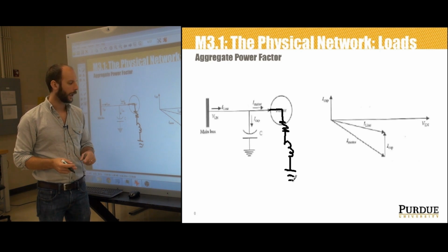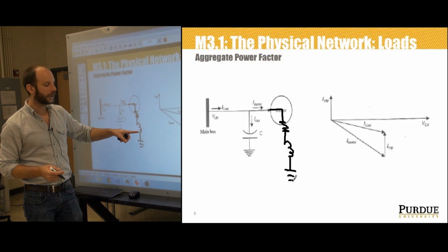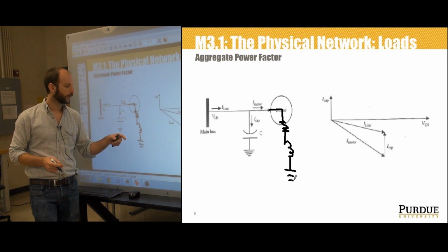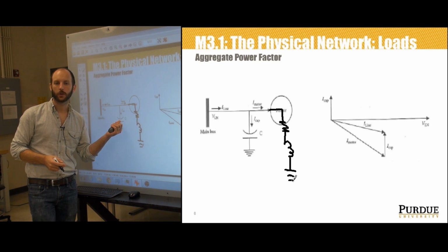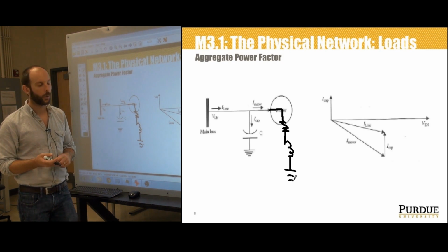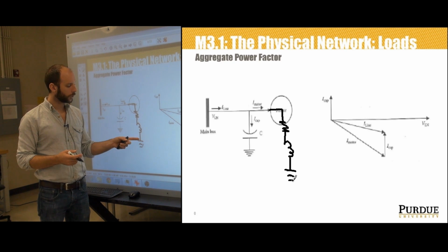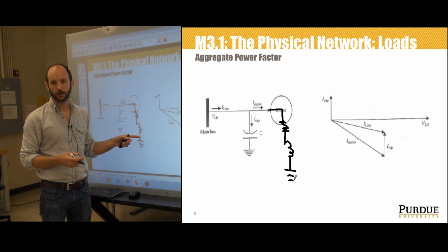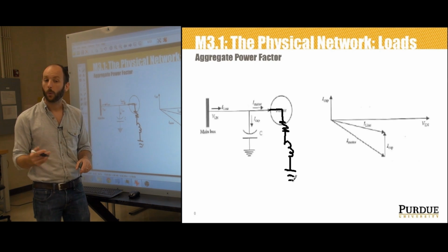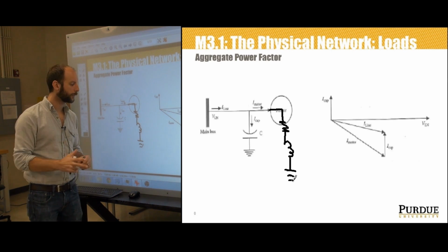circuit model. And what we want to do is cancel out the inductive reactance of this. What we do is we put in a capacitor in parallel with it. Why in parallel? Well, we could put it in series and they would directly add, right? That's kind of a novice circuit analysis technique. Let's just put that in series. What's the problem? Two major problems.